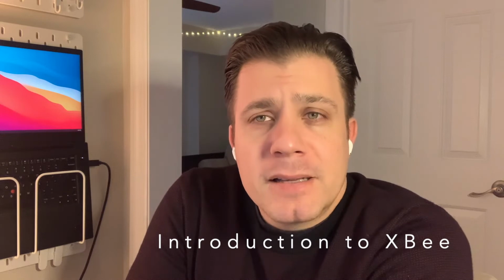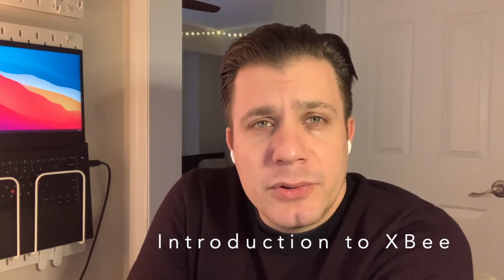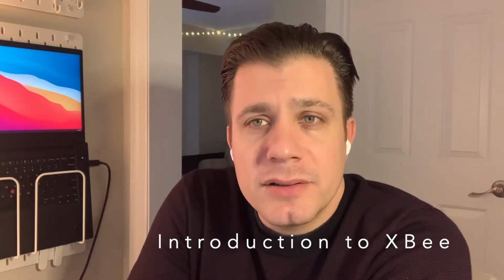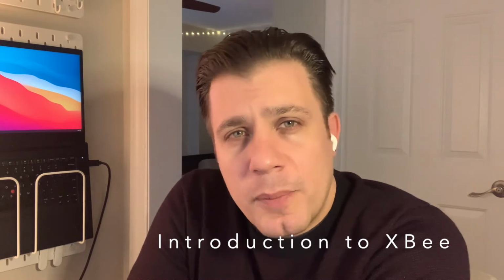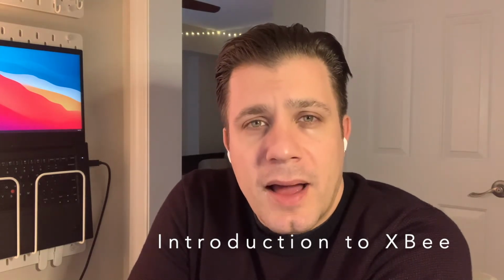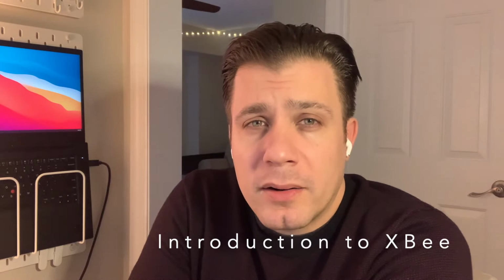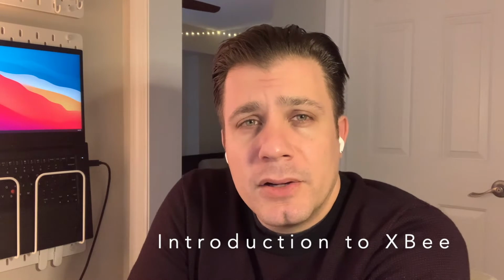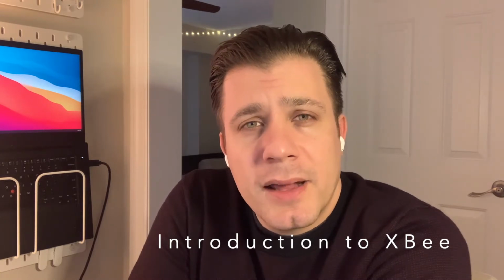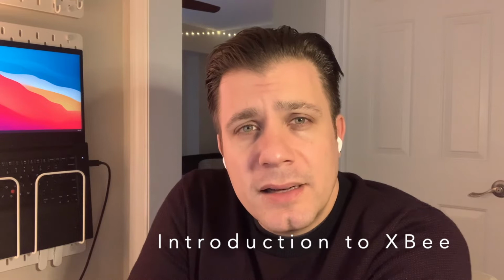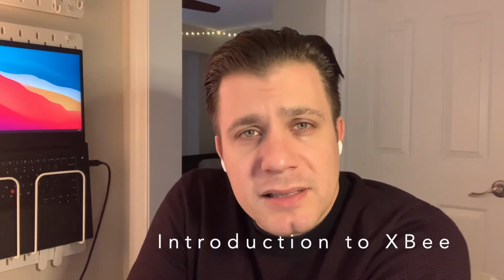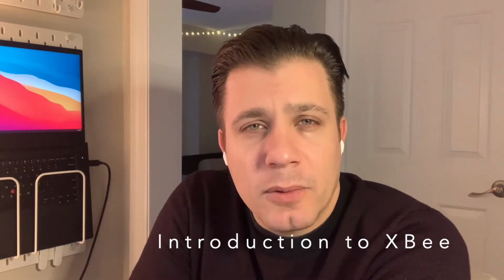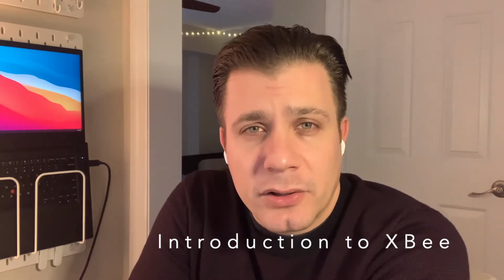What is ZigBee? ZigBee is an IEEE 802.15.4 base specification for higher level communications. It's focused primarily on low power, low data rate applications, and those that really only require communication over smaller, closer proximities. They're used to create personal area networks, and one of their strengths is they're intended to be simpler and less expensive and less complicated than Bluetooth or Wi-Fi networks, and definitely cheaper than cellular, which would require some sort